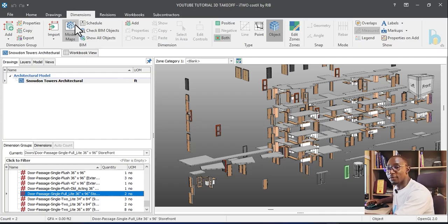So you can verify and filter within them easily. You have your external separate, you have your internal separate. And you can also separate them using material type, whether flush door, metal, aluminum, steel, and so on. You can filter using that. So we are going to do that using the model tree when we get there.